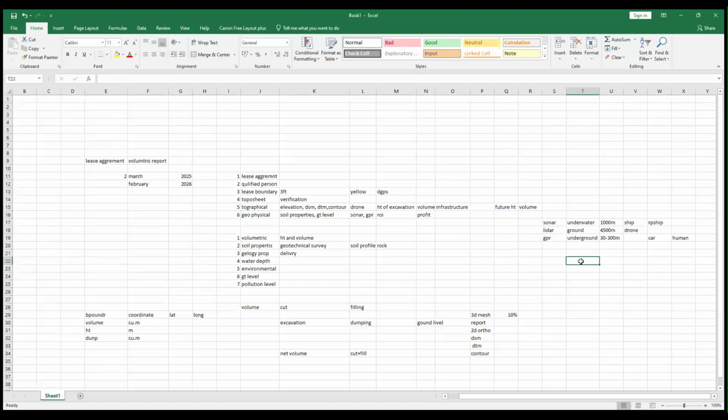There are some softwares like Bentley which will process and repair equipment data, just like our image processing, where we use Pix4D for photos. There are image processing tools like Bentley MicroStation and all other things, and there is a tool for DJI also, where the DJI Matrice series has a LiDAR payload. They have their own processing software which combines all the LiDAR output and gives you a proper full file. Just like your image, it will give you the LiDAR details of the full stretch you are surveying. It will do internal processing using the cloud and give you that. Other than this, there is not much for a geological survey or anything.